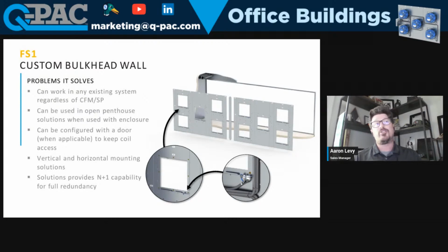Next one. We can also do vertical and horizontal mounting. A lot of systems you find could be up blast or down blast type systems. I don't tend to recommend laying a horizontal system for a down blast system, mainly because you need access to the fans, and they're going to be on the underside. But for an up blast system, the system can sit flat, and we may need some structure depending on the dimensions of the system, but they can be mounted in either direction.